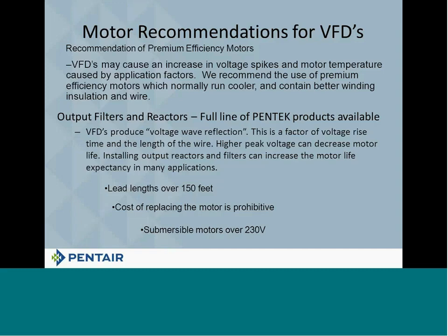But the bottom line is the rest of the world all runs on metric, and they use a 380 volt system. So a 380 volt system is greater than 230 volts, and the bottom line is you can now get that sine wave to really peak up there and hurt things. So that's why we say any submersible motor over 230 volts, you should be putting something on it.